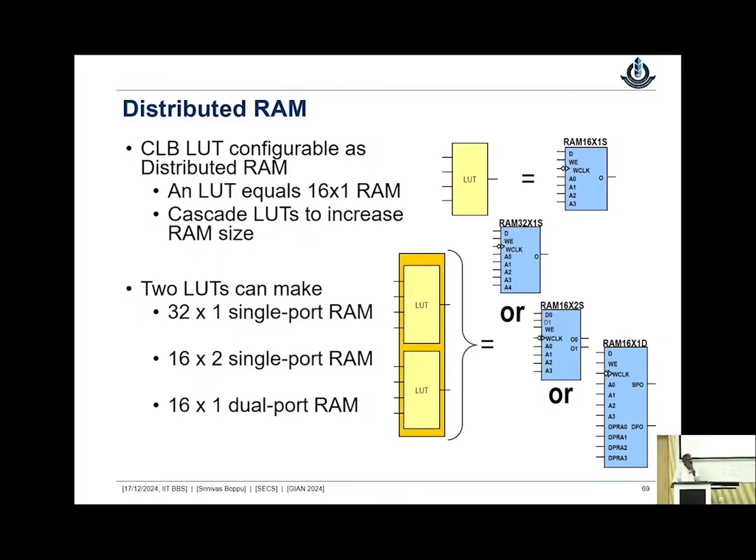So now if you want to realize a 16-bit register, I can also go ahead and do it, right? Now if I want to use a 32 by 1 bit memory, I can use 2 of them, right? Okay. So if I have 2 of them, I can also say that it's 16 multiplied by 2 also, right? So this is implementing the 0th bit position, and this is implementing the 1st bit position. I can also combine such LUTs, and then I can implement 16 locations, maybe 8 of them I can combine. So 0th bit, 1st bit, 2nd bit, and I can extend it, right?